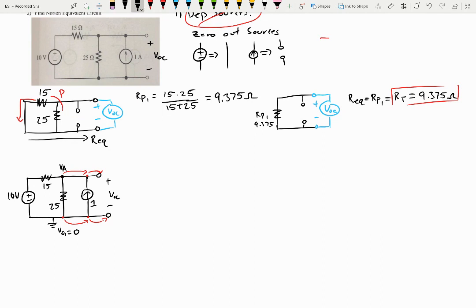You can name them whatever you want. Okay. So V of A, what we're going to do is assume that all of our currents at this node are leaving, except for known current directions. So right here, this is coming up, it's 1 amp, and it's going to have to pass into V of A. It can't go down this open terminal, so it has to go that way, so it's entering.